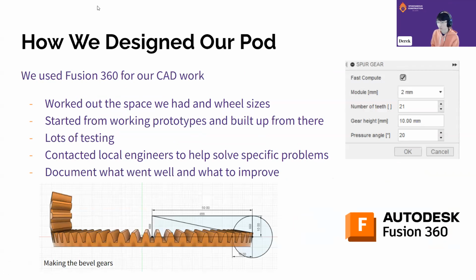And then essentially what you would do with that profile is align it with the diagonal line of the rectangle. Because two bevel gears essentially are just two cones rotating on each other. And to get the length and height of it, you would create a big rectangle, as you can see. And then the distance from one end to the other end is the actual angle of your bevel gear. And you would set the spur gear tooth profile perpendicular to that line, and then use the circular pattern tool to create all of your gear teeth. Hope that makes sense. Yeah.